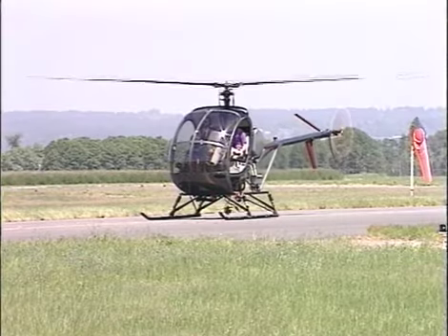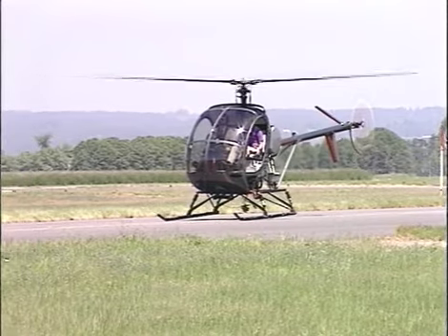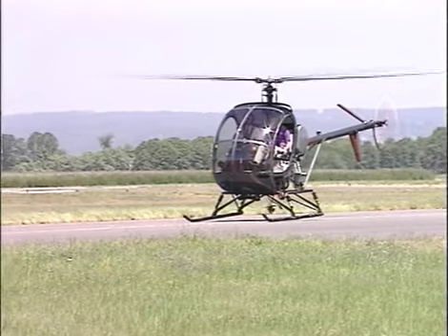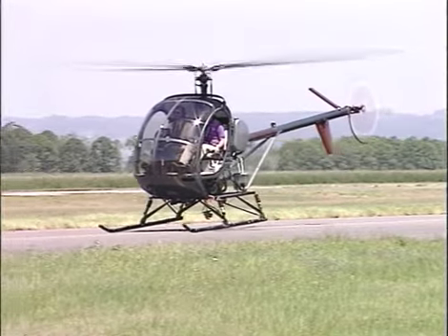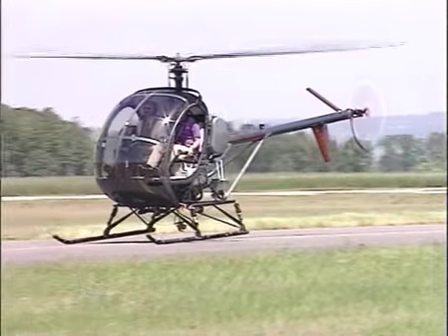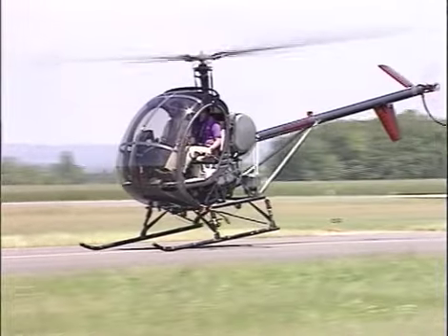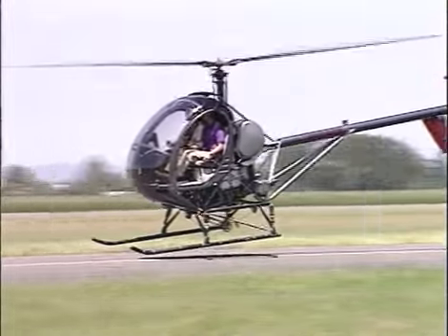Another fact that most people don't know is that helicopters, even those with skids, are capable of running along the ground for takeoff and landing at speeds up to 20 miles per hour. Use a running takeoff when high weight or high density altitude prevents a sustained hover at normal hovering altitude. Don't attempt a running takeoff unless the helicopter can hover at least momentarily, because performance will be unpredictable and there may not be enough power to safely get the aircraft off the ground.